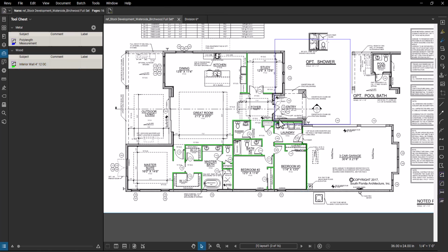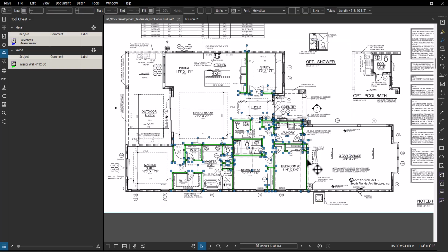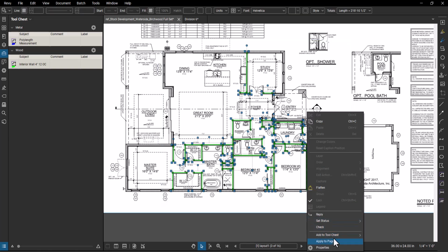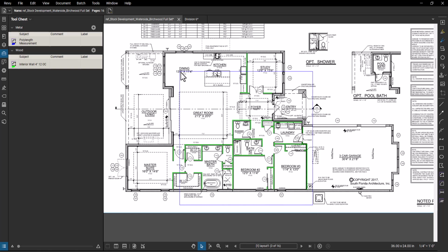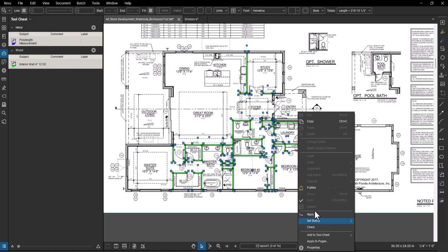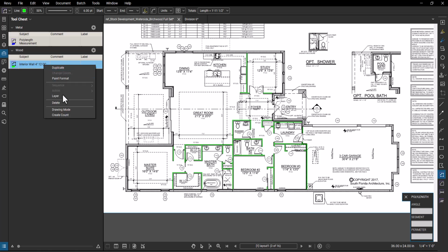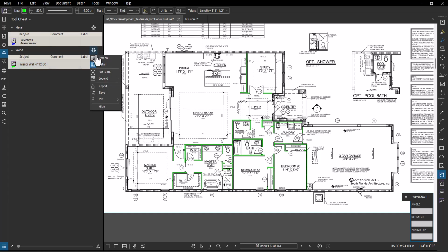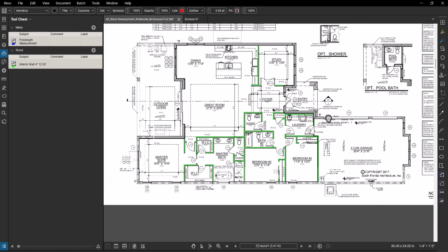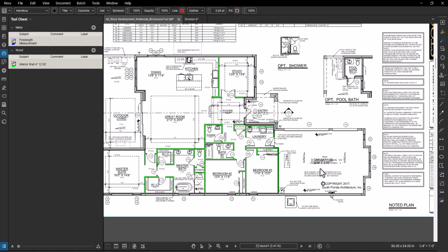What I can do, I'm gonna select the whole thing, and I will right click, and I'm gonna create a legend for that one. So it's hard to select that because there's some other thing over here. So I can do like this, right click over here, and legend. So you need to click on the wheel over here, legend, create new legend, and then I'm gonna put it somewhere, maybe here.